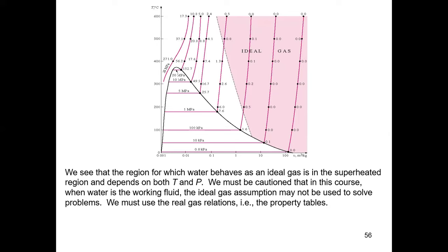We must be cautioned that in this course, when water is the working fluid, the ideal gas assumption may not be used to solve problems. We must use the real gas relation, that is, the property tables.